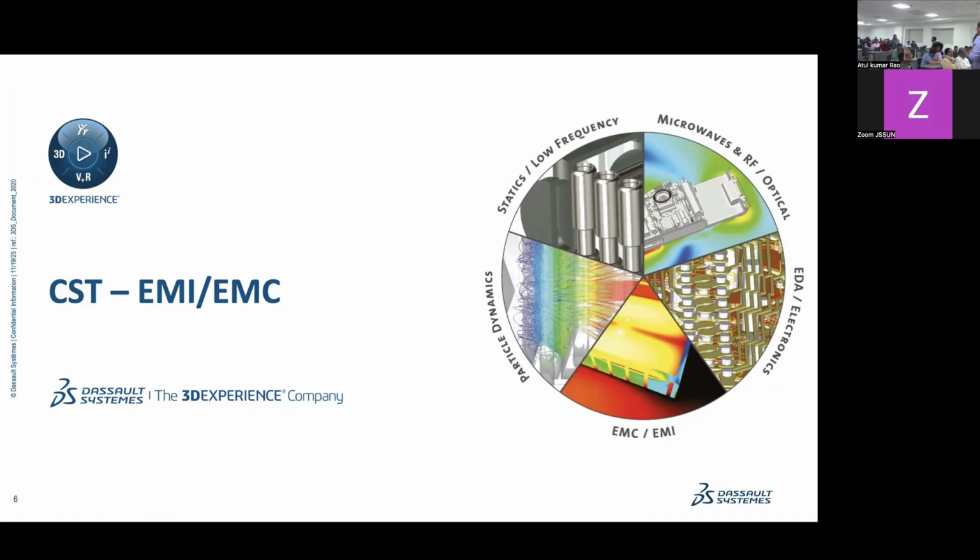So you use an approach called the SAM approach, right? SAM stands for System Assembly and Modeling. You break down the problem into two parts. One part is specifically for the antenna, where we use one specific solver, and the second part is for the car itself. The car can use a different solver, considering the field source from the first one. So that's the approach that we would have.